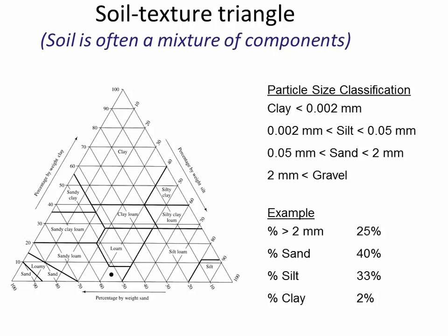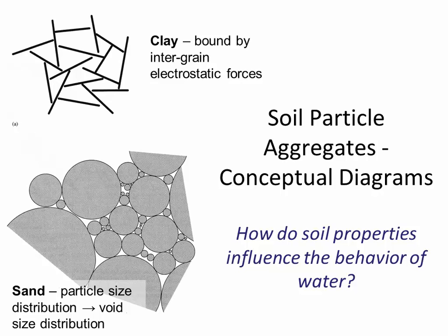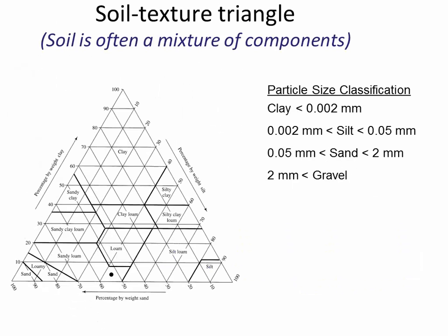And so there's a whole range of possibilities of different percentages of clay, silt, and sand. Even if we have a large field and we dig down and take a sample at one location, it may be some percentage of each of these. But then what we call sand is also itself going to have a variety of sand grain sizes. Back to this figure, even though this is 100% sand, the sand grains are varying in size. And so soil is very complex in terms of what it's made out of, the variety of sizes, and also the spatial distribution. Within a watershed, it may be like a clay silt on one end of a watershed, and it may be more sandy on the other end of a watershed.